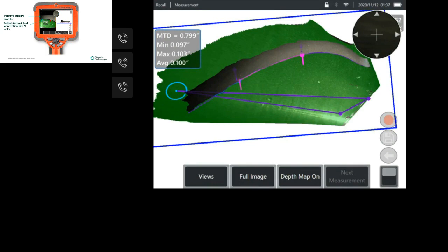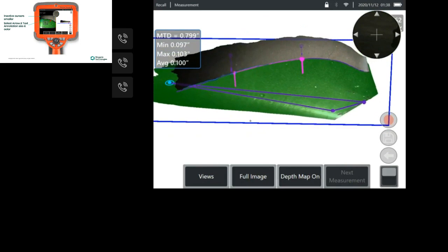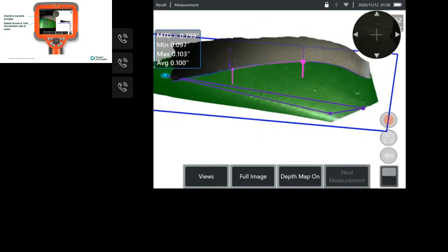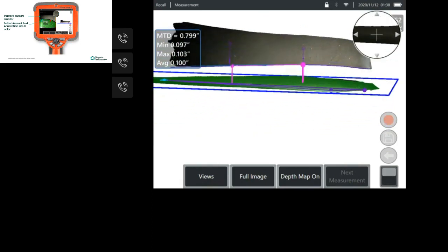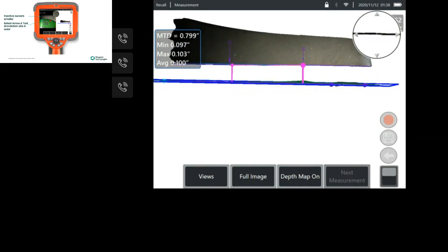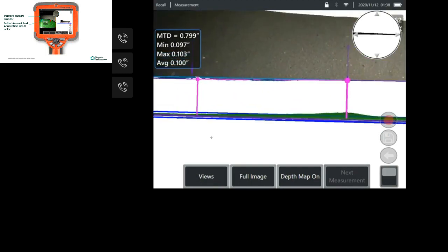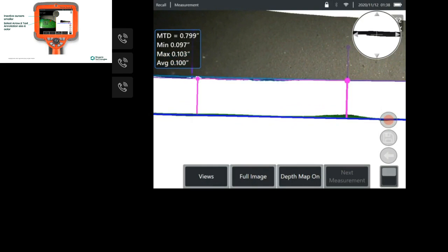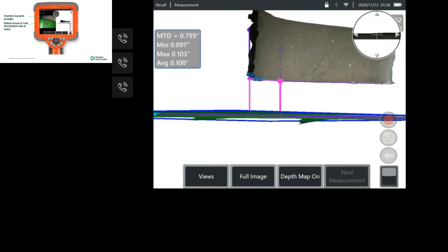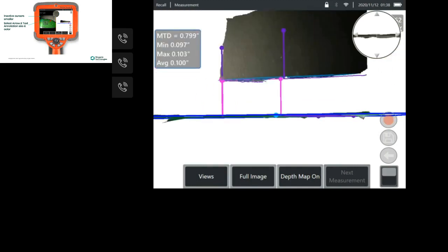And data that's green, and I rotate it on the side here, you'll notice that data is all very close to that mathematical plane established by those 3 cursors. I often use the terminology clean point cloud or noisy point cloud. That point cloud that's masked in green is so clean that it is razor thin. I see no noise or Z points going above that plane. So I'm feeling really confident in the depth value with this measurement.